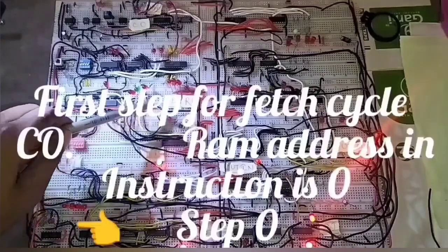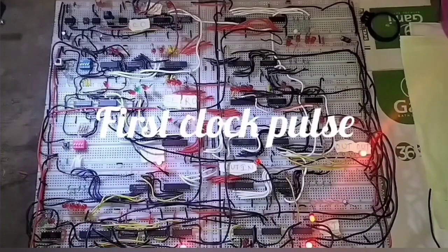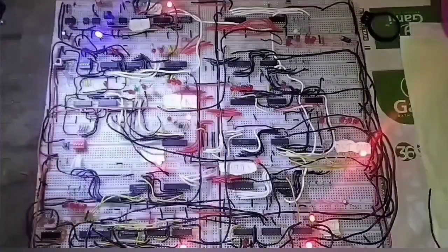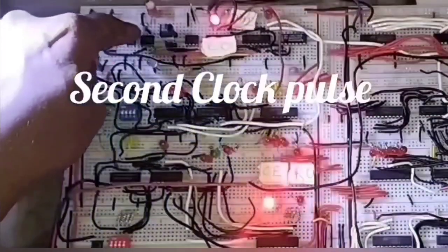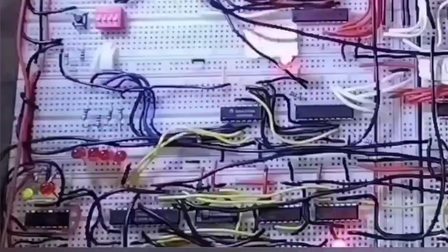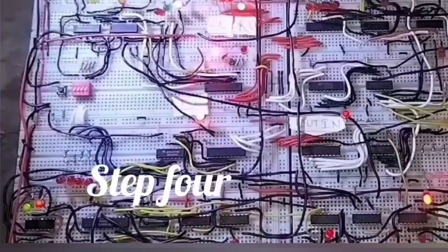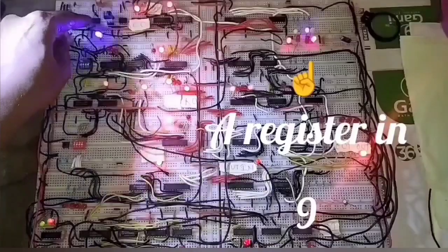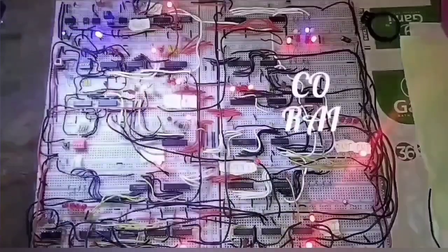Let's see the fetching and execution process of the program. Here I am giving a total of 20 clock pulses. Each instruction will take 4 clock pulses. Load A will take 4 clock pulses, load B will take 4 clock pulses, and the out instruction will only take 3 clock pulses. One will do nothing. The jump instruction will take 4 clock pulses and will go into the infinite loop after that.